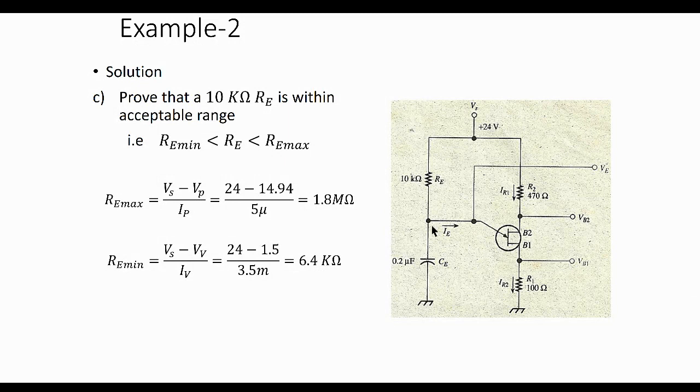So key point. You need to pay attention to the manufacturer's data sheet so that you can select your components properly. As you can see here, you couldn't just arbitrarily place a value of resistor here for a particular frequency, right?